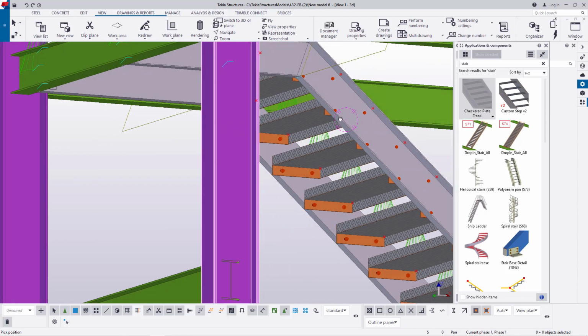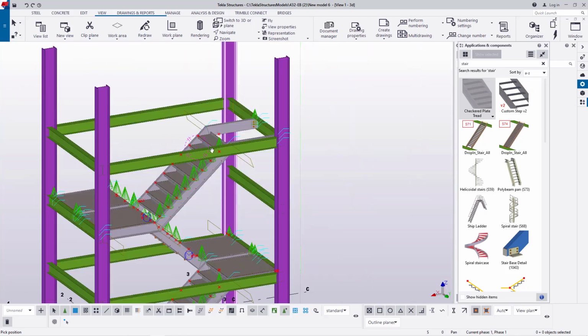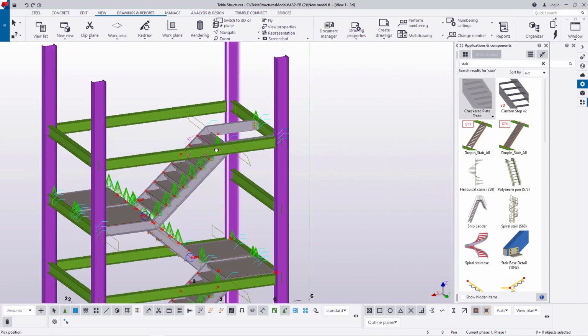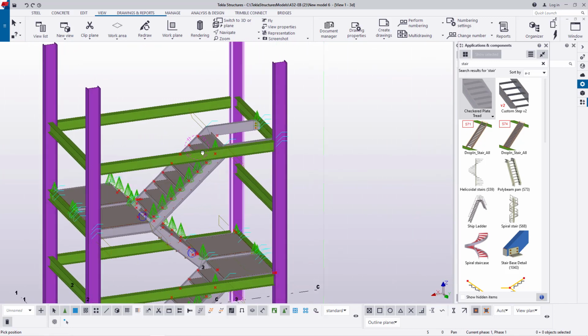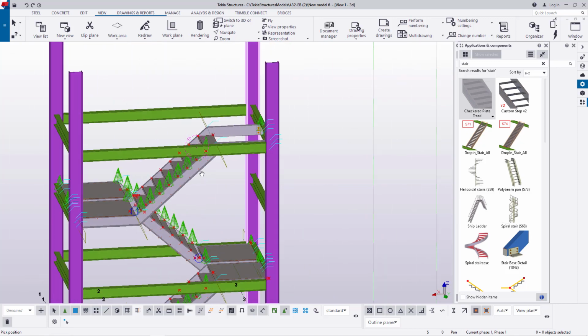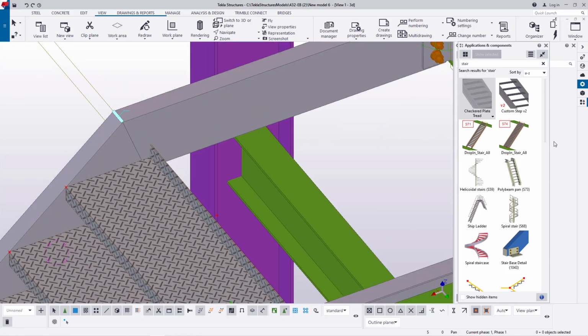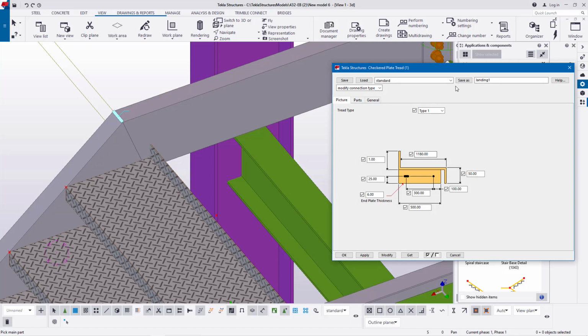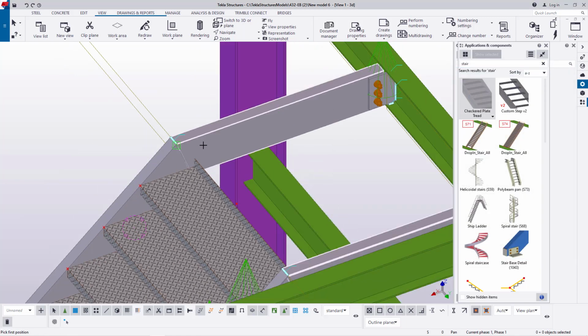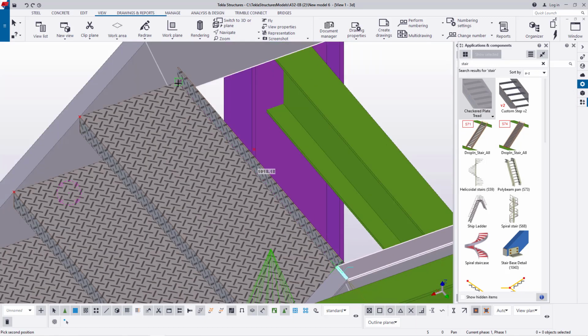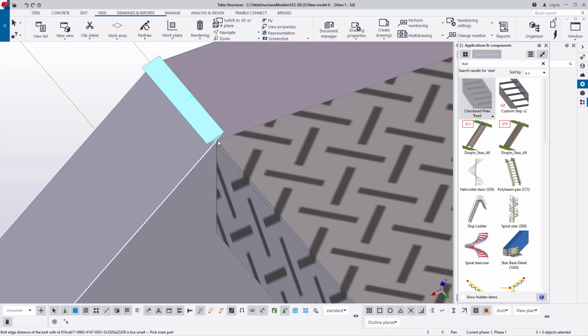I'll come to navigate and turn that round like that, and I'll be able to see that I need another thread on top here. So the stringers that will be copied with it will be this stringer and this stringer that will be distributed up all the way to a height of my choice. Now I'll double click on that, and maybe I'll choose my previous landing, and I'll load it, modify, give it an OK, apply it. I'll select on that and select on this, then snap on that spot and move all the way to that end and place it right there.